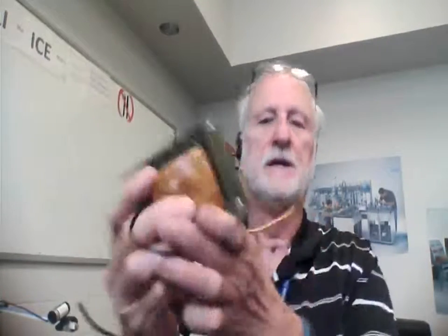So what do we use to concentrate magnetic fields? When I come up here and look at this transformer, which is doing the same principle, I see this big chunk of metal right there, because what do metals do? Metals concentrate magnetic fields. Ferrous metals do; aluminum works crummy. If you can't pick it up with a magnet, then it wouldn't concentrate a magnetic field, right? Y'all understand that?